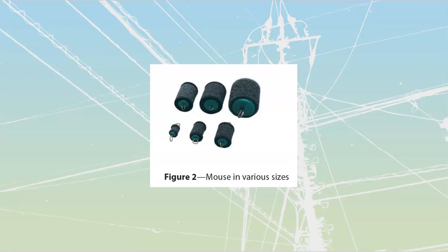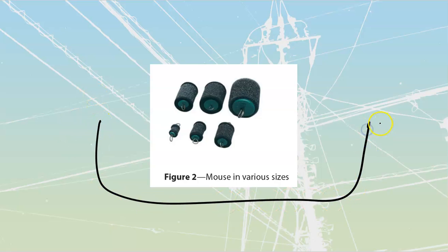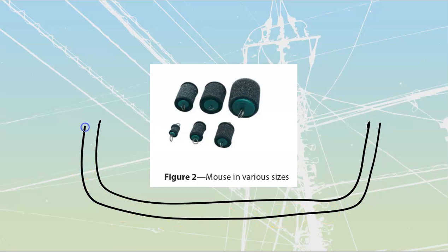If it's a long run, we are going to use a mouse or a bag or something like that. It's very common. You should have all experienced this at some point, where you have a conduit and you're going to bag the conduit, where the conduit just goes underground from here to here. What you'll do is attach a vacuum cleaner, just a shop vac. That's a terrible looking shop vac, but whatever. Attach the shop vac on so it's over top of that thing, so it's going to be pulling suction.